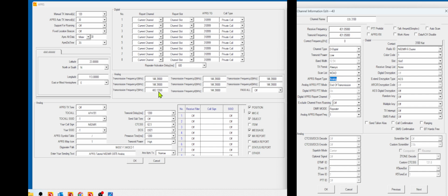And this would be a repeater that would be on a different frequency than the APRS national. It'd be a local frequency. You're not sending it worldwide or America-wide or North America-wide, and so that's why they allow you to have that. And also, folks that travel to different countries will have a different APRS frequency for their analog signals.